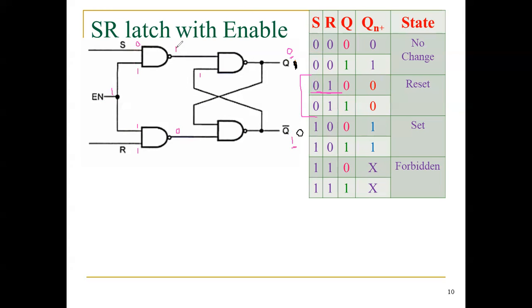So that gives here 1, 0. Since the output of this one equal to 0, that makes this 0 as 1. This 1 now comes to here. Therefore, all the applied inputs of my N3 equal to 1. Hence, my output is changing into 0 for my second assumption.